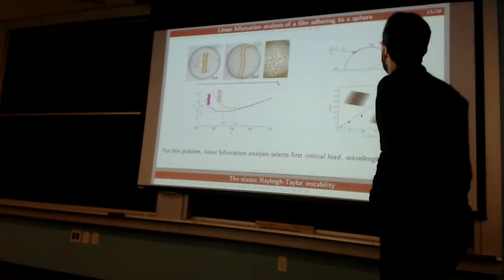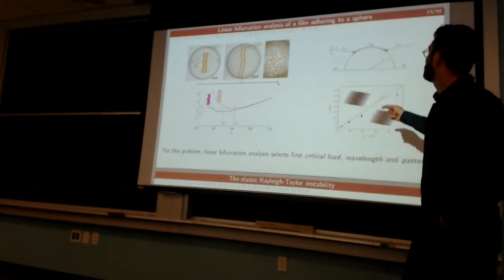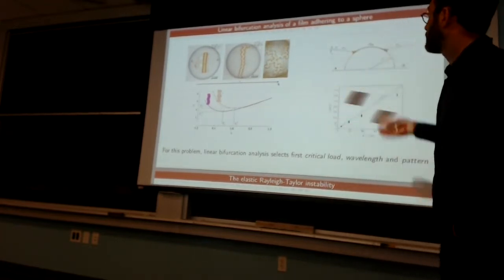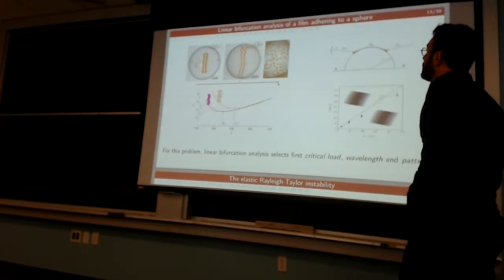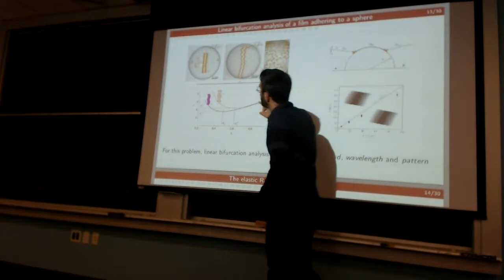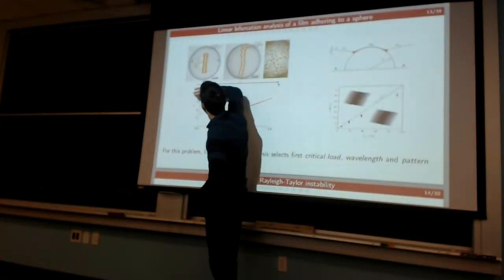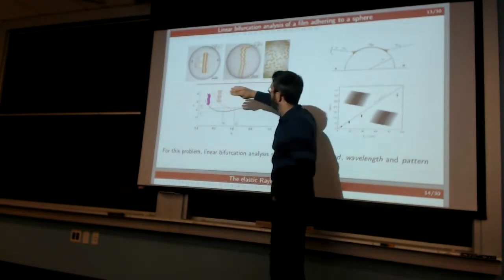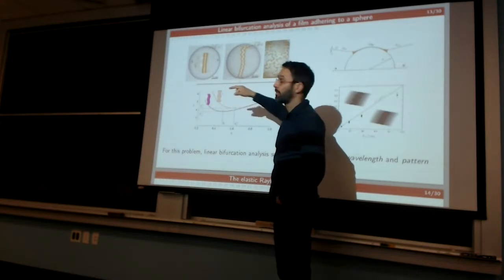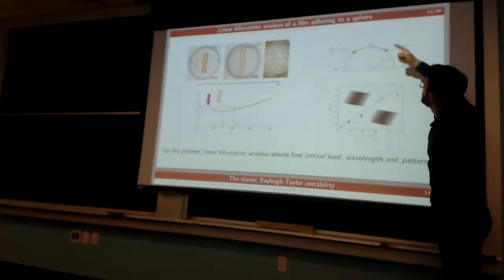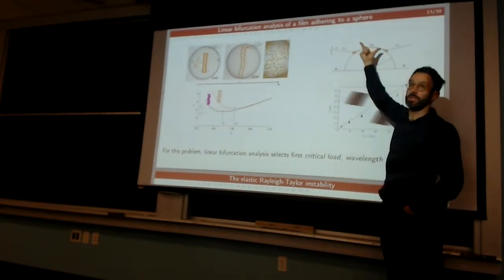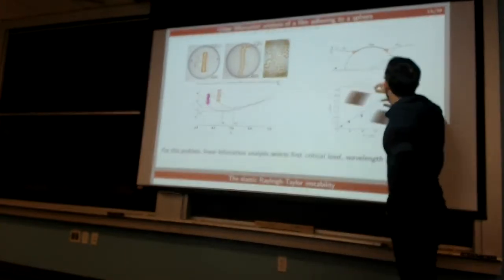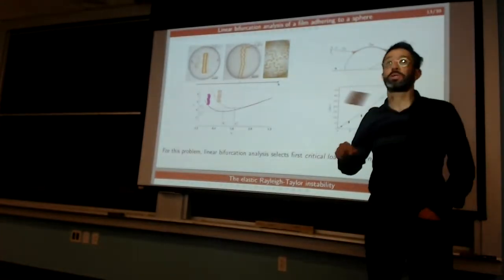So that's a complex problem. There are some boundary conditions that take into account the capillary bridge. The shell's equations are not super easy either, but for that problem, you can identify a reasonably simple solution, and that's shown here. It's the case where the cylinder has a shape that's axisymmetric, like in this drawing. Then there's a rectangular region of contact here, which is what you see here in yellow. And that's what we will use as the fundamental branch, right?